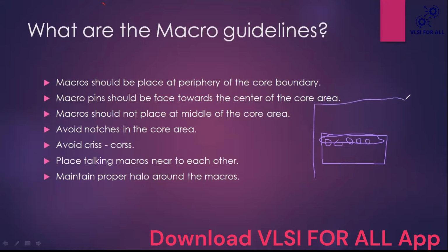Consider the outer square as the core. This is a macro. So these pins should face towards the center of the core area. Consider this as the center of the core area. All the macro pins should face towards the center.